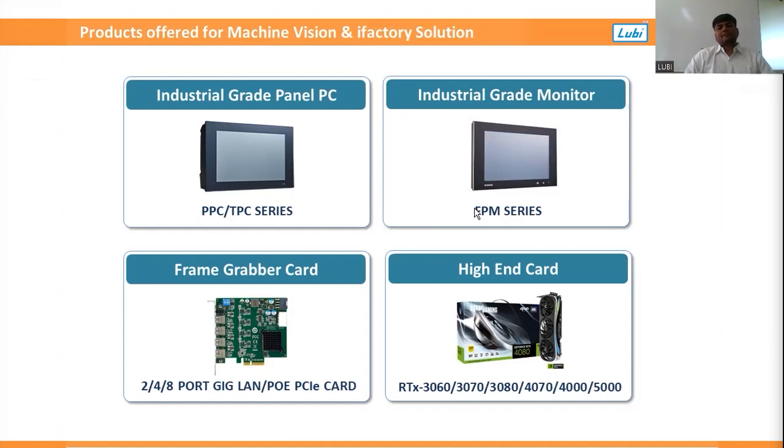instead of a commercial PC, why do people choose industrial grade PCs? The first one is reliability. Second, high-end temperature. Third, high vibration levels, because it will run 24 by 7. Higher connectivity like serial COM port, Ethernet port, PCI slot, PCI Express slot. High-end graphic cards we can install inside this. Durability and continuity. One of the major constraints for end users or end plants is continuity. Because if any industrial grade PC model is launched, it will continue up to 7 to 10 years.